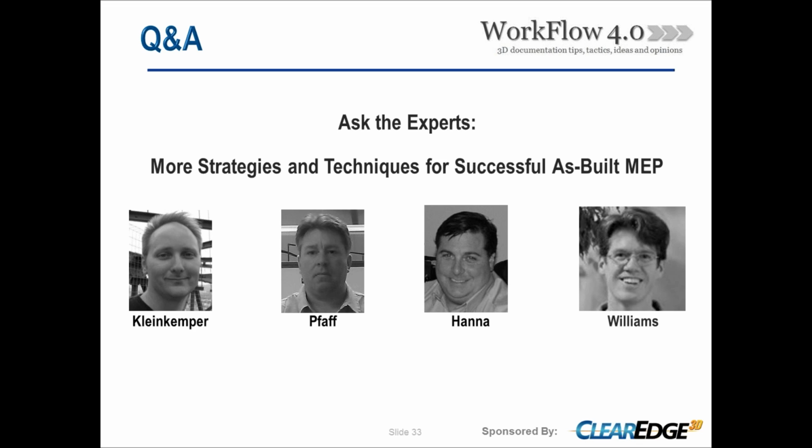Anybody else want to weigh in on that one? Yeah, I think Mike's points are spot on there. It really comes down to survey control. There are inherent inaccuracies in the scanner, so relying on good survey control and adjustment techniques is really just going to make your scan data that much tighter and your registrations better. Okay.